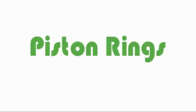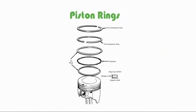Piston rings. Piston rings provide a sliding seal between the outer edge of the piston and the inner edge of the cylinder. The rings serve two purposes. They prevent the fuel-air mixture and exhaust in the combustion chamber from leaking into the sump during compression and combustion. They keep oil in the sump from leaking into the combustion area, where it would be burned and lost.